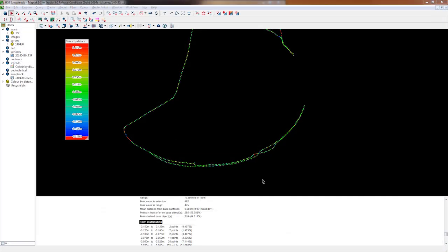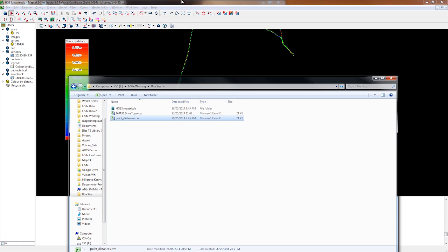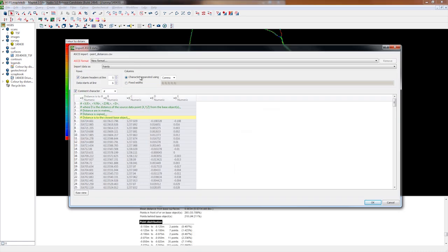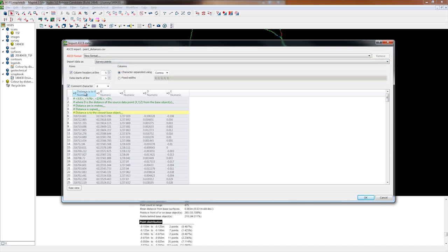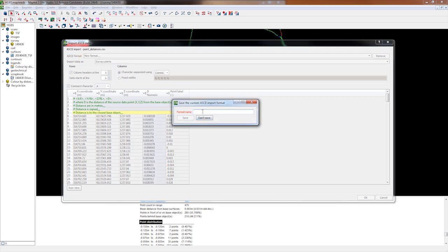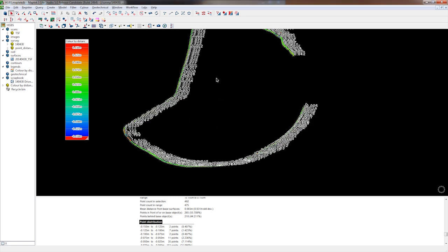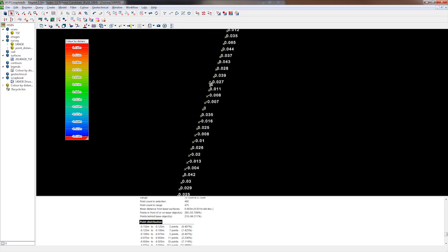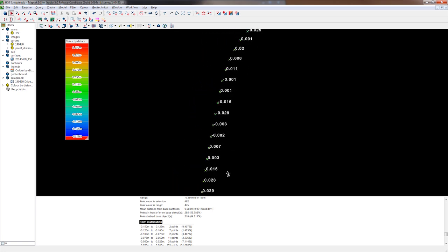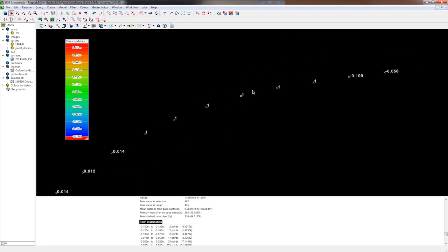And now you'll see when I import that in, what will happen if I go down to custom. I need to import this as survey points and then specify the X, Y, Z coordinates and then my truncated column as my label. If you're doing this all the time, we can save it as distances, for example, and instead of going custom, I can just select distances, and here you can see all of my measured distances. Where it's 0, it's smaller than a millimeter, and where it's 1, it's outside of my tolerance.